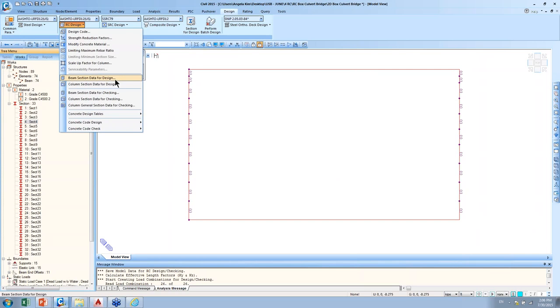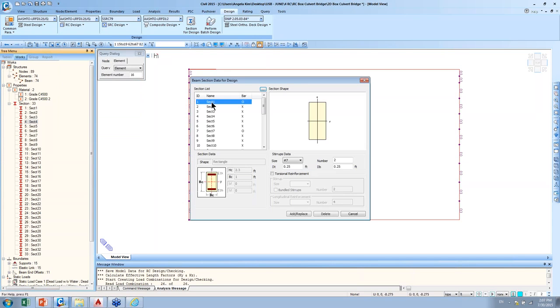So you can actually enter the rebar for two different types, design and checking. Design will let you know the rebar information, and checking will let you know the actual strength and the crack section check. Design rebars are relatively simpler. As you can tell, you simply input the stirrup data and any torsional reinforcement rebar data.